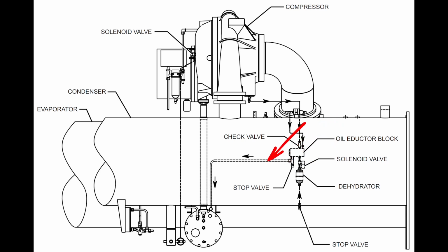Either way, this is just the YK example. We've got our medium pressure oil line coming back into here and hitting our block. We also have a vapor vent line coming off of the oil sump that returns up to our suction and hits the side of the compressor up here so that we're able to vent. This line here is not a vent. It's a drain that allows the oil that gets into our scroll or rotor assembly, where the gears and stuff are, to drain down into our sump. That's what this pipe is doing.